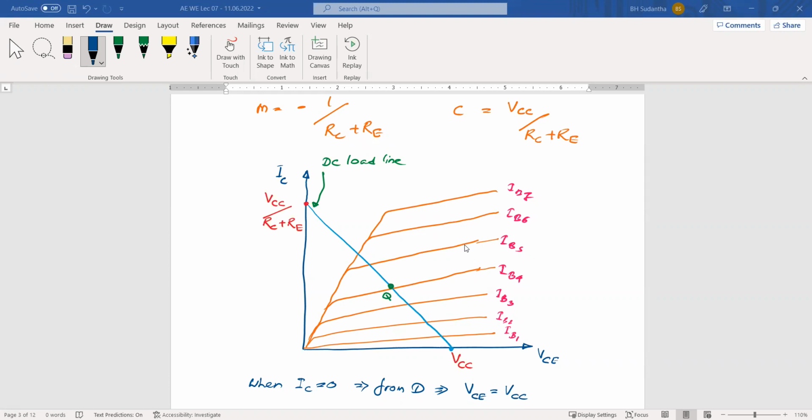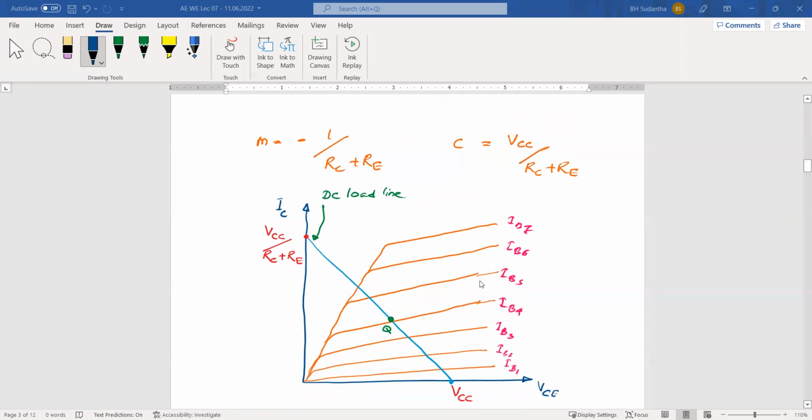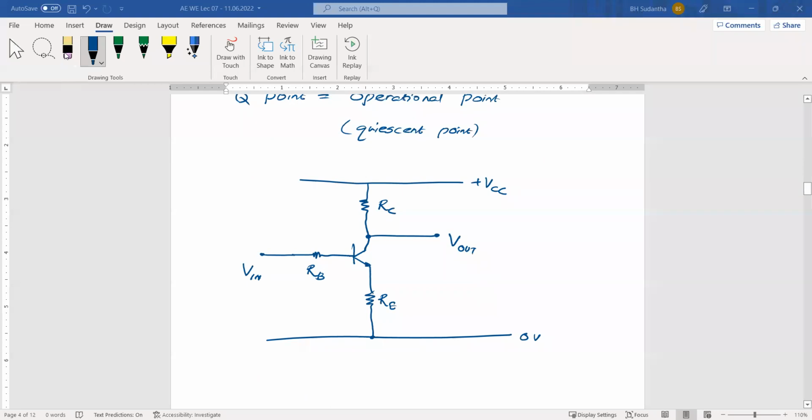And to do that, we have to turn on the transistor by providing some current, IB, or voltage VB. We have to bring the transistor somewhere here. This arrangement is not working, so we have to provide a certain voltage to this point. Then these voltages are fixed. We place the transistor's operating point in the middle when we carefully select this RB and RC couple. After that, you can give another voltage here.